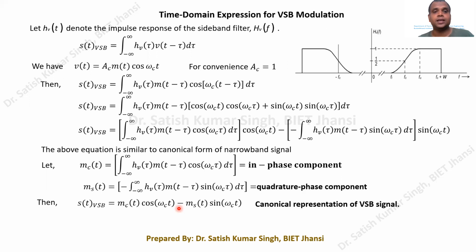The second thing we have to understand is, in the case of the DSBSC signal, can we send it through DSBSC? We cannot, because of the requirement of large bandwidth, since the video signal itself occupies 4.5 megahertz. If you send this signal through the DSBSC modulation scheme, it will occupy a bandwidth of 9 megahertz, and that bandwidth requirement is very high. Therefore we are looking for a technique in which the bandwidth requirement can be made as small as possible.